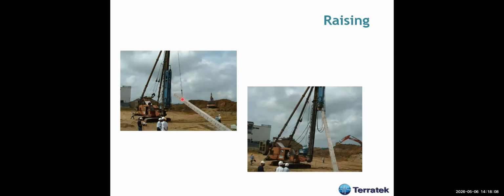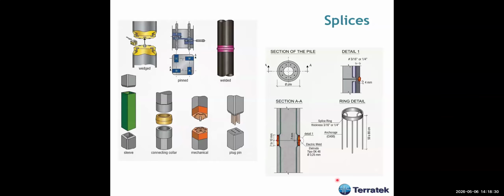And this is raising the pile. You have to do it very carefully. Usually you have to pay attention to the prescription from the manufacturer on how to handle and raise the pile in order to avoid damage to the pile. They can break if you do it wrongly. And here you raise, you prepare for installation. Then there's the case of splices. They are different. Every manufacturer has a different type of splice. One of the most common for spun piles is this type of splice, in which we have welds.